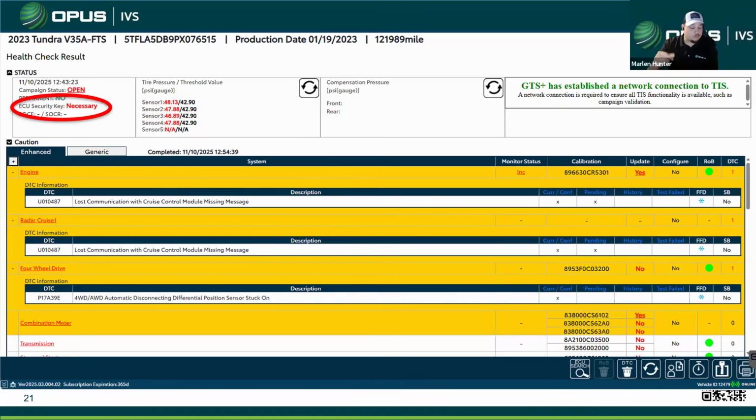Now, what I didn't show, because you don't get a lot of them, but it does happen, is that some cars usually have a 360 camera. You'll go through and do the same procedure, but it requires a target board to be behind the car, set up in space like you would for most ADAS. Now that's usually for the higher end model XLEs and things like that. I've probably only done a few of those, but that one you'd have to, again, go to service information, measure it out, and have the target in place, and that way you can get your 360 camera working as well.